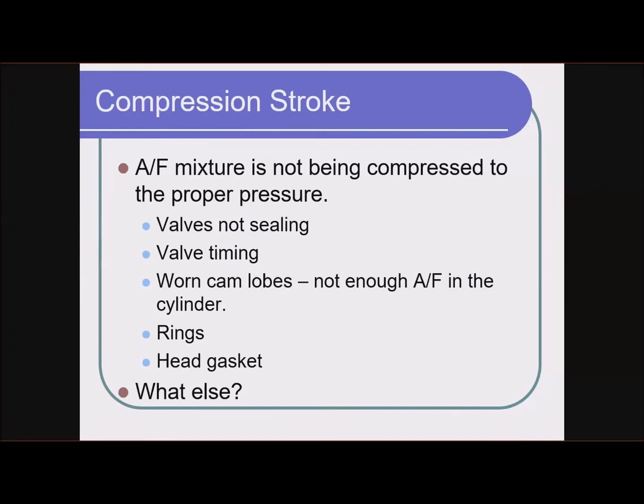If we have worn cam lobes, let's say a worn intake cam lobe, and we don't take in enough air, that can cause our compression pressures to be low. How about worn rings, or a bad head gasket?